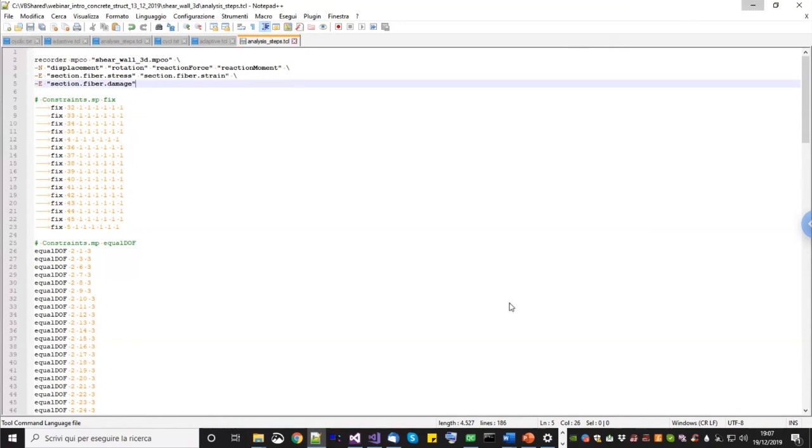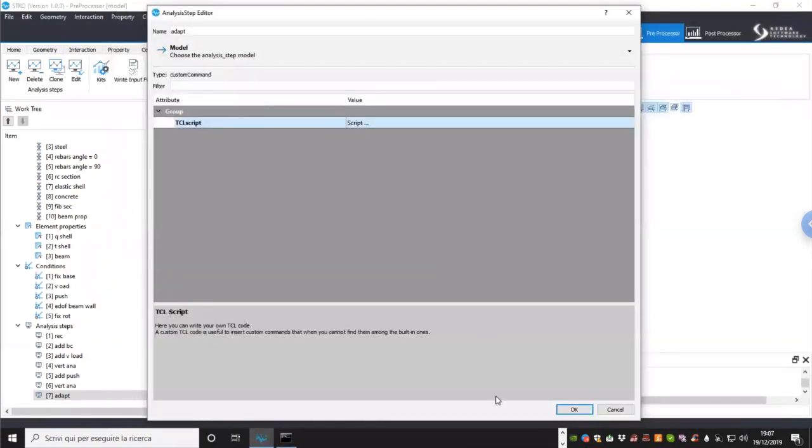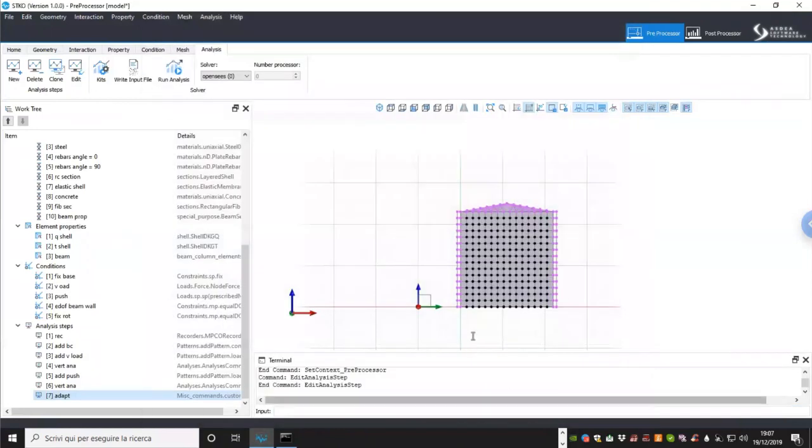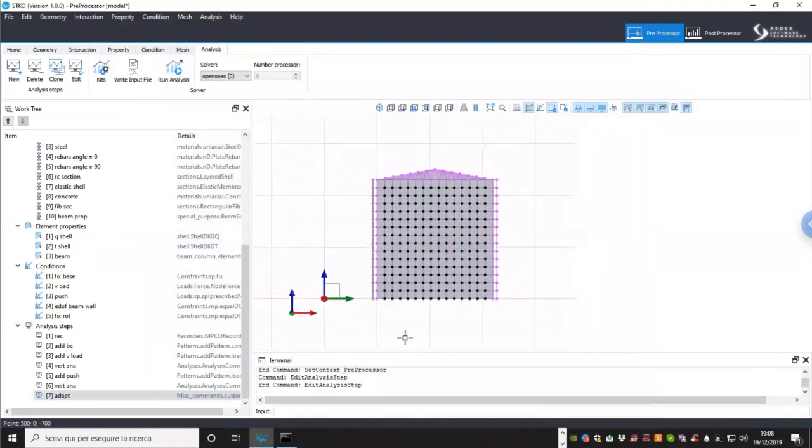Obviously, the model that is shown is also the concrete damage model. The damage plasticity model can also be used for masonry, and the one that we use for masonry we showed a bit. I also saw that there is this nice option of implicit-explicit. Is that something that is available in OpenSees already? Actually, this model has been implemented by us in our local version of OpenSees. And if you download STKO from the website, this version of OpenSees is already included, but you should not belong to an Italian institution. But you're in Bristol, so there is no problem.